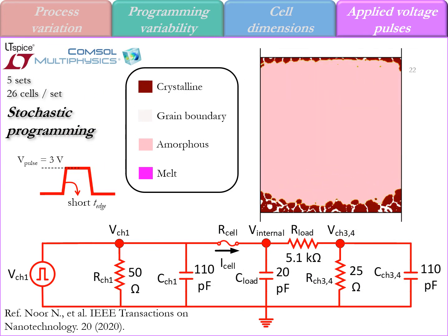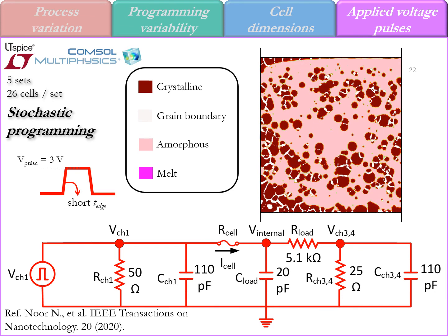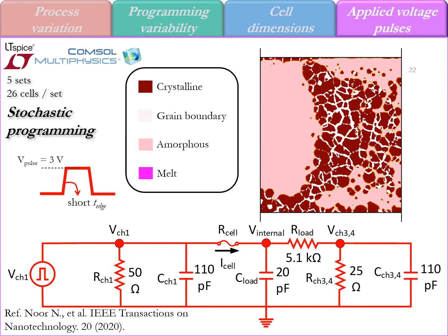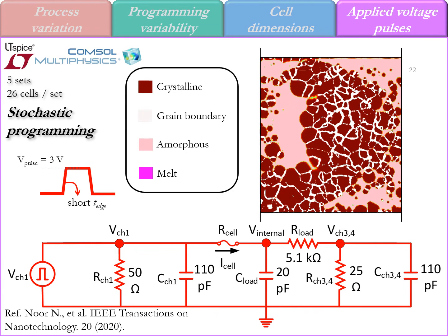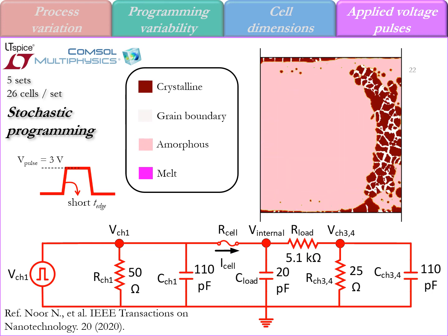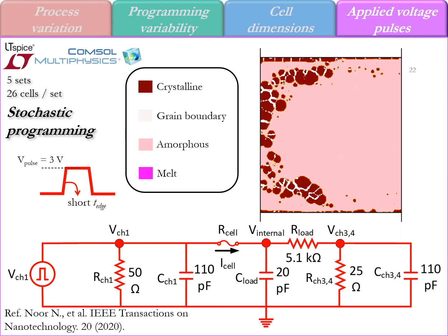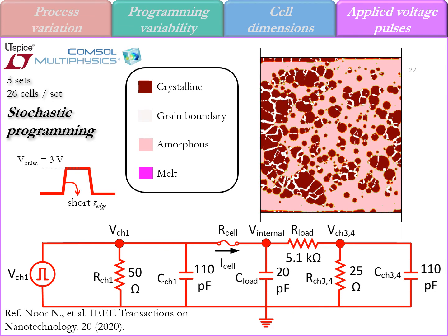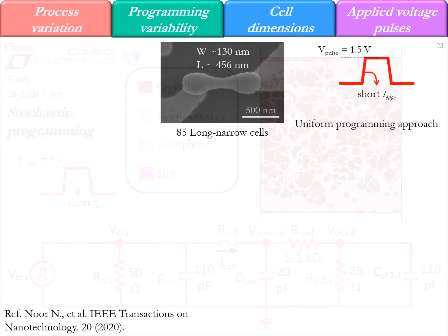Apart from the variations, we also had some parasitic components in the experimental circuitry. From our detailed SPICE circuit simulations and finite element device modeling results, we observed significant variations in the melting locations and the crystalline grain distribution map after each reset pulse on the same cell was applied. These parasitic components can be easily integrated along with the PCM cells to enhance the reset variability.